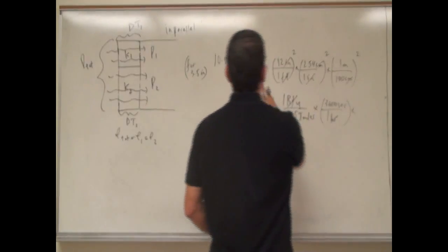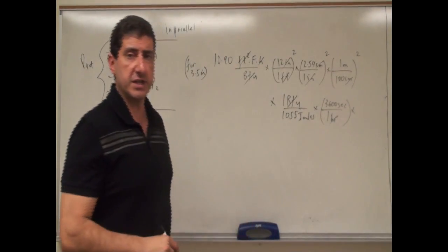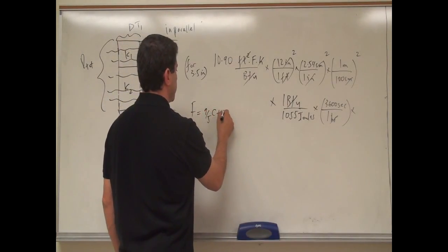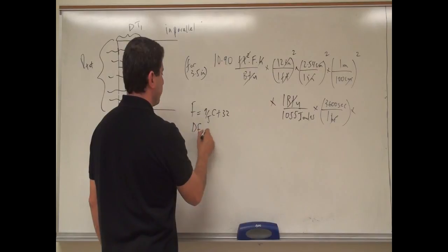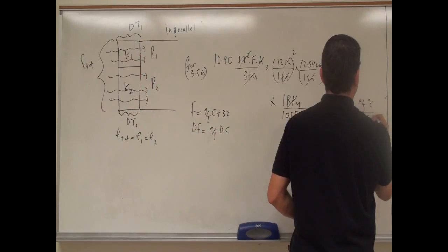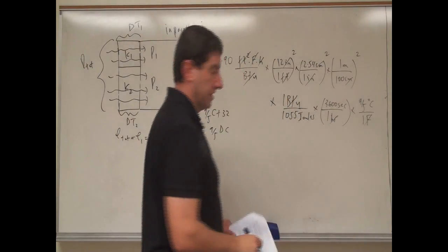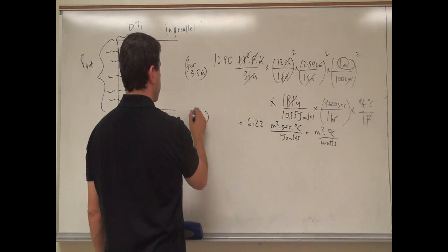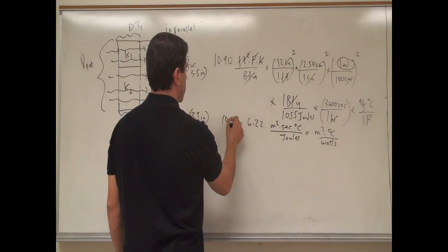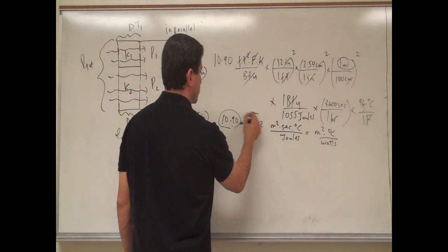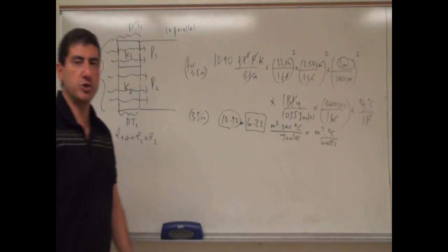And then how about the conversion between Fahrenheit and Celsius? Well, remember the equation, Fahrenheit is 9/5 Celsius plus 32. So 1 change of Fahrenheit is equal to 9/5 change of Celsius, right? So the Fahrenheit and the Fahrenheit cancel, right? So you can see for a 3.5-inch fiberglass, the 10.9 that it had for the insulation factor turns out to be 6.22 in metric units, right?